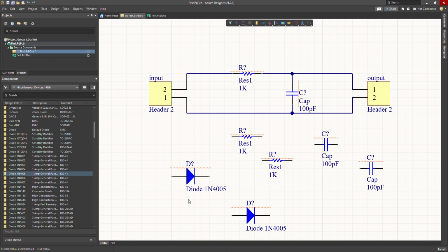Now, as you noticed, I pressed annotate schematics quietly, which means it doesn't ask you for any properties or any characteristics of how you want to annotate the components. But if you want to define how the components are annotated, you can go to Annotation, Annotate Schematics, and ignoring all of the other stuff that is going on here, it can give you some more options on how to annotate more precisely.